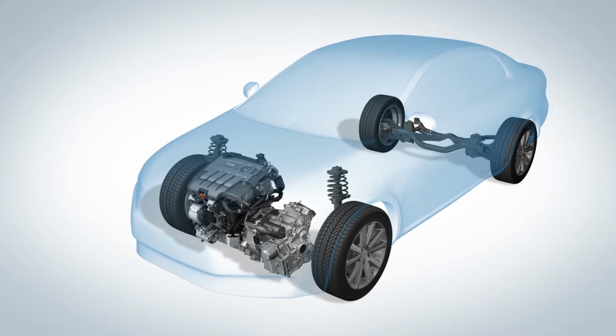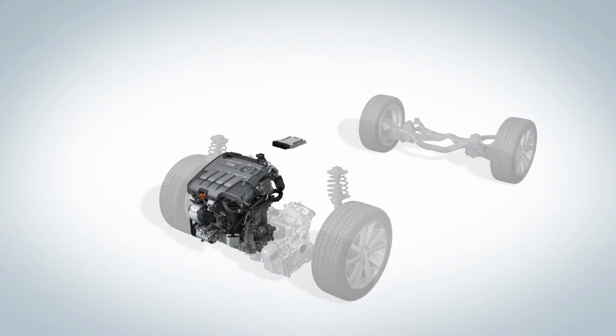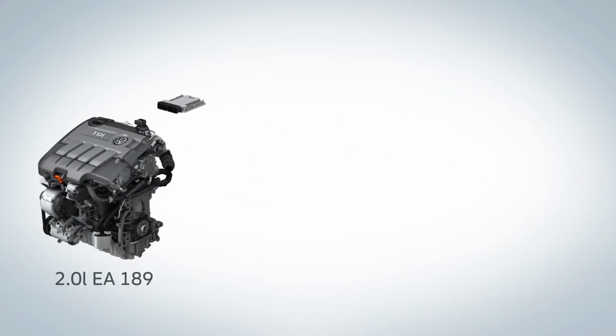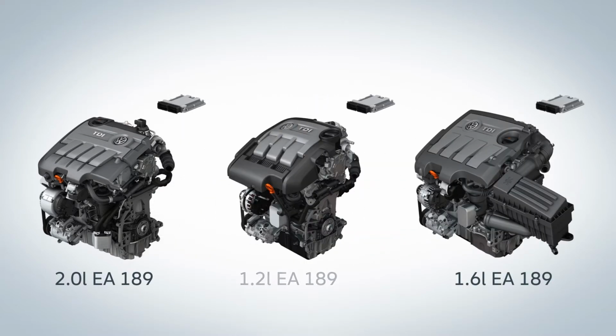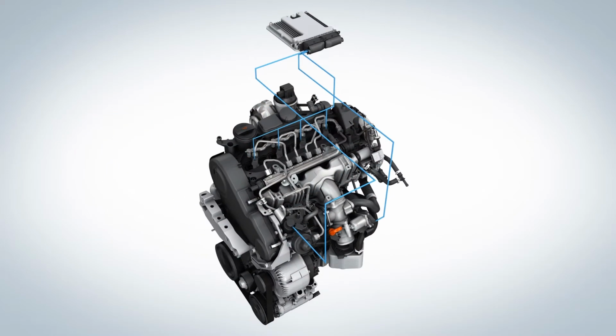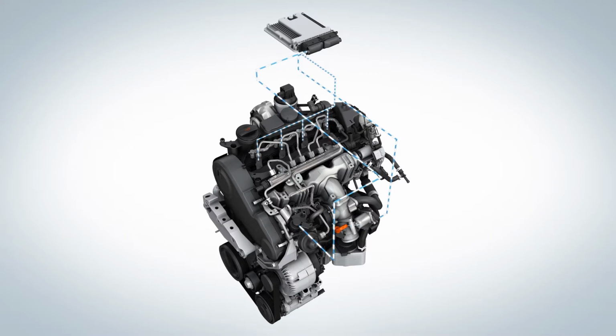We have developed technical measures. The updated engine control software eliminates the switching function that enabled the engine to switch to a particulate-optimized or NOx-optimized mode. These differ for EA189 engines in Europe, depending on the engine type. All engines get a software update. The adapted software ensures that the combustion is always carried out in a NOx-optimized mode.